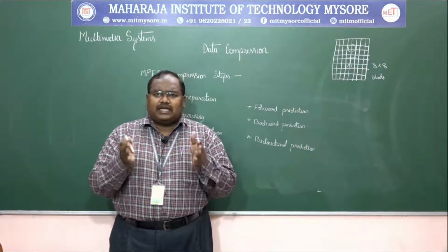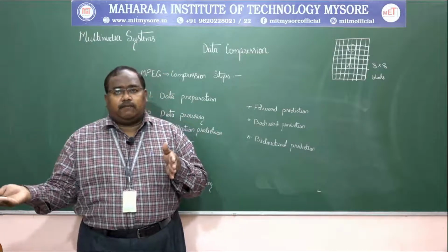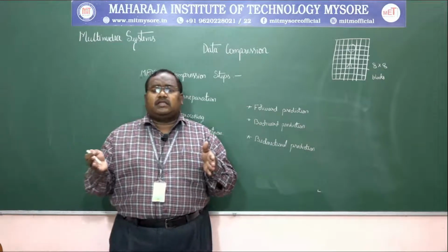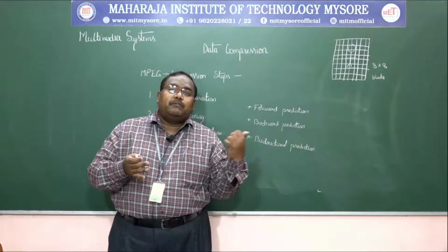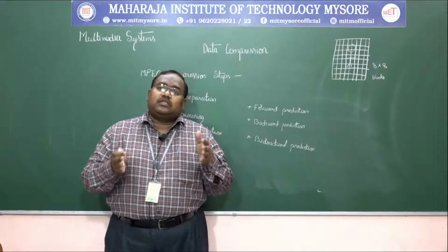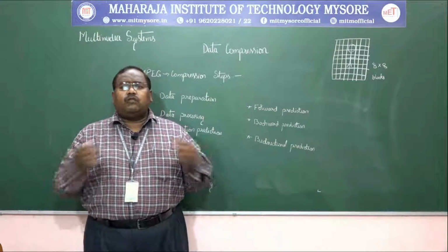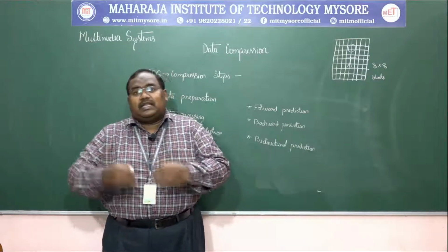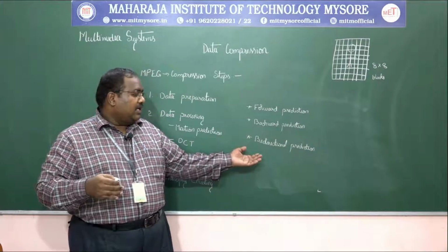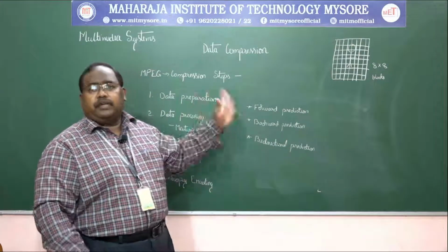Sometimes we analyze the current frame and try to assess what could be the next frame. In particular cases we use the current frame and predict what the previous frame was. This is called backward and the previous one was called forward. The combination of both kinds of prediction, what was the previous and what would be the next frame, is said to be bidirectional prediction.